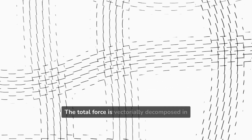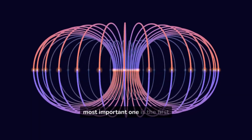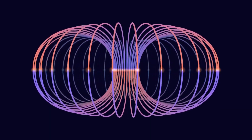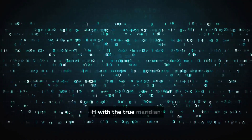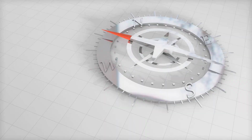The total force is vectorially decomposed in two directions, one the horizontal H and the other the vertical Z. The most important one is the first, H, which is the one that orientates the compass. The angle that H forms with the true meridian in T is called magnetic declination or local variation.